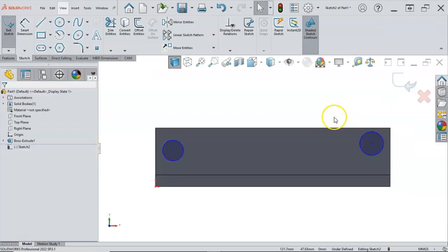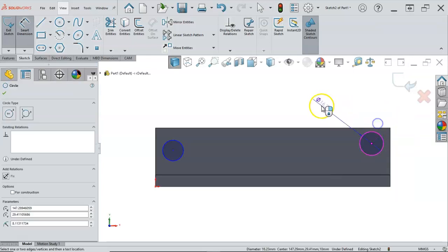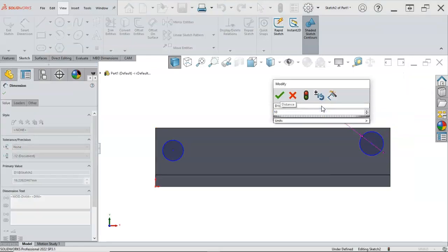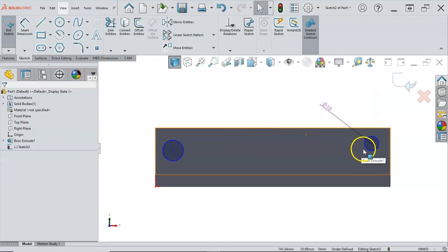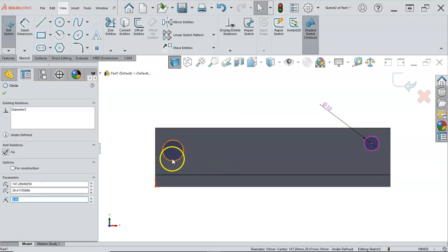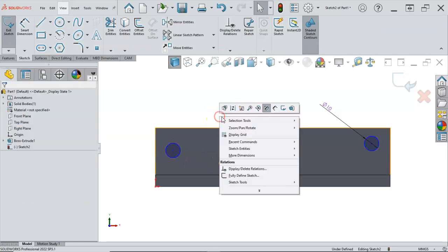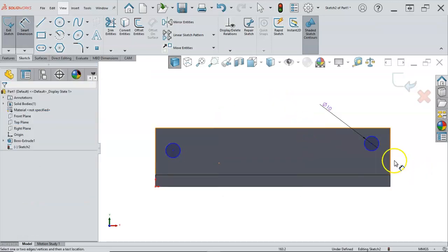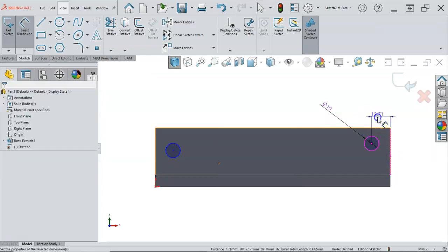If you put them at the same level, that's fine. I mean, it's not called out, so there's kind of an assumption there, but I don't think it's really that big of a deal for this part. So 10 millimeters, and I'm going to select, control select, make those equal, and then with the radius of 12, I'm going to set those center.